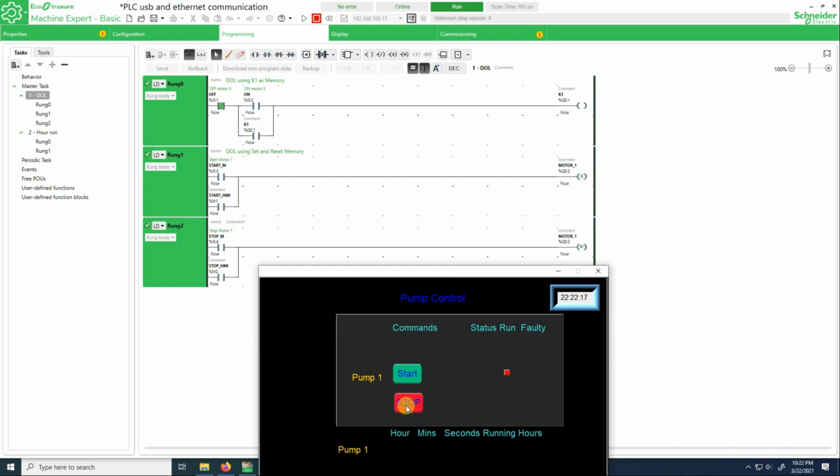Okay. As you can see, when I press start, which is here, and you can also see here this one will be activated. I just press it again, you see. So from an HMI I can control the start command, and this will activate the set register. So to stop it, this one is a M2 address. This will write to this register M2.